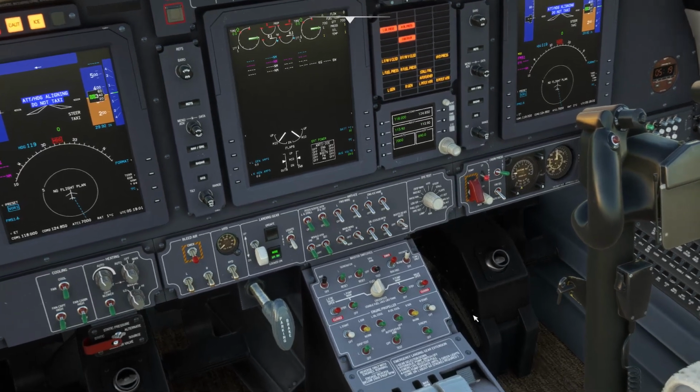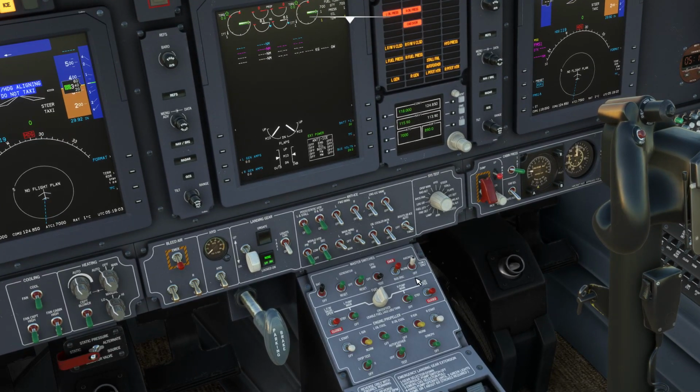If you don't have GPU and you want a quick start, then you move it to COM1 only, just to get the clearance, and then you move on to engine start, and once you have at least one engine running, then you can move to avionics. However, there are a few conditions there, which we will not be getting to at this moment.